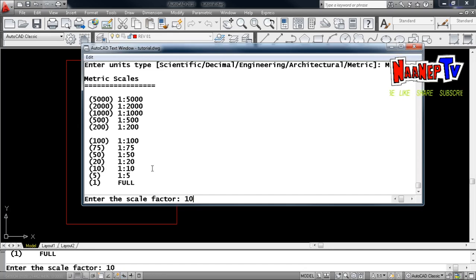By the way, for the scale, if you're in building construction, please do not use other scales than these. Do not use an uneven scale. It is not acceptable, say 1 is to 32, 1 is to 64. These scales are standard. It should be at least by tens.